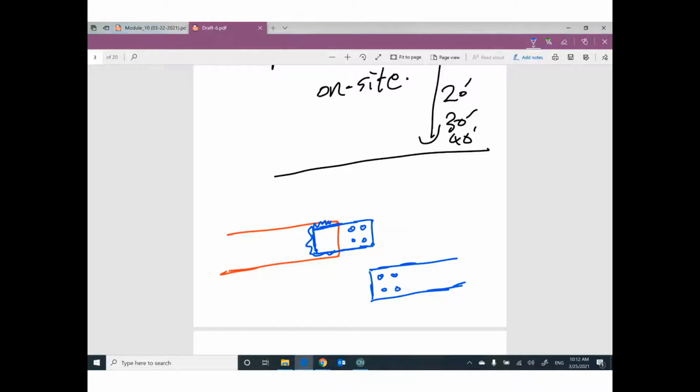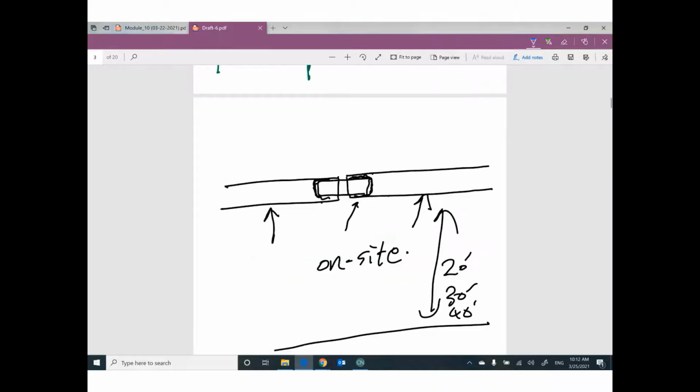In a few seconds or minutes, we can keep both of them together here, put your bolts in, and tie them. That's all. But for me, I believe all splice connections would be bolted from the two sides. I didn't see one side welded and the other side bolted.